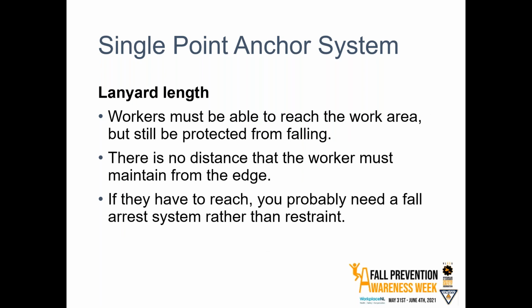Another really important piece, which I alluded to earlier, is the length of that lanyard or lifeline. Again, the whole purpose of this lanyard or lifeline is it's meant to be only just so long as they can reach just the edge, or for that matter, if they don't need to get to the edge, it needs to be just long enough so that they can get to the work area without falling.